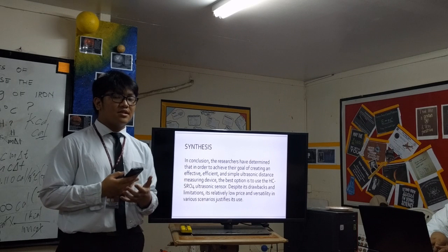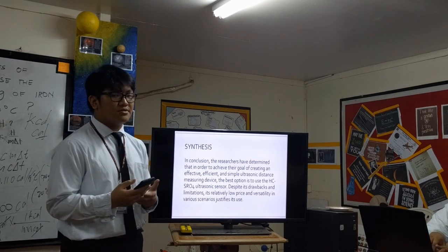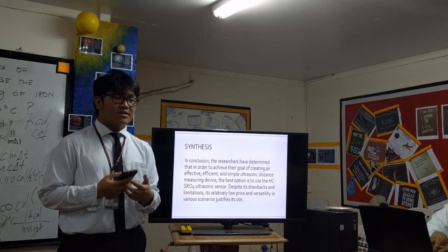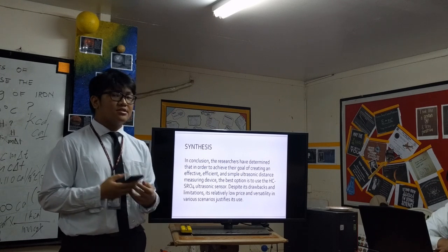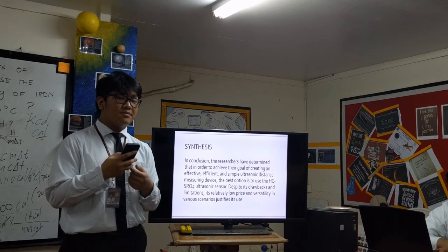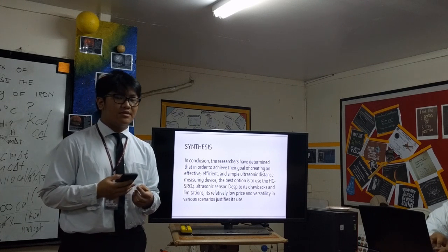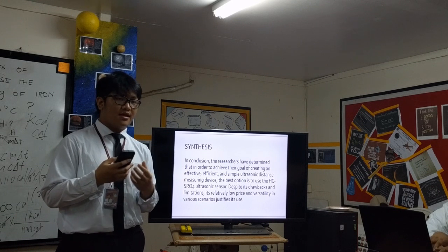It doesn't have to be physically in contact with the object that it tries to measure. Next, in order to be non-contact, it uses the pulse method. Basically, the transducer emits a pulse of ultrasonic sound waves in microseconds. These pulses will allow us to measure the distance between the device and the object.